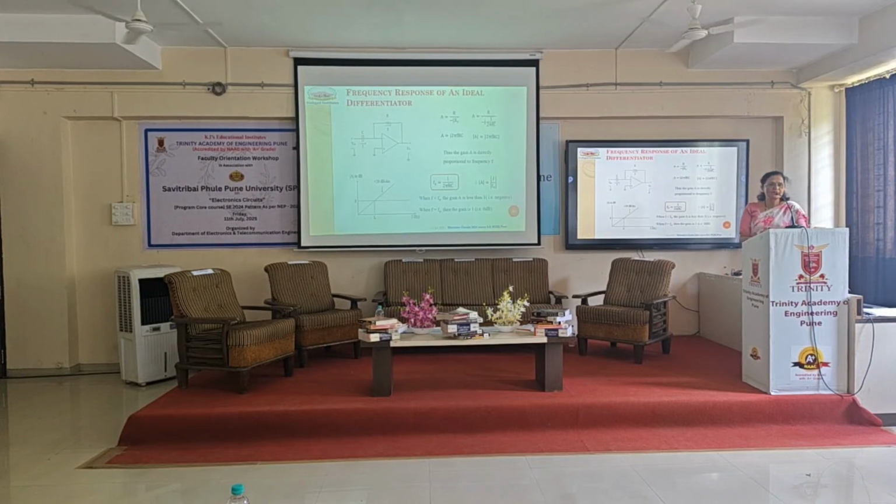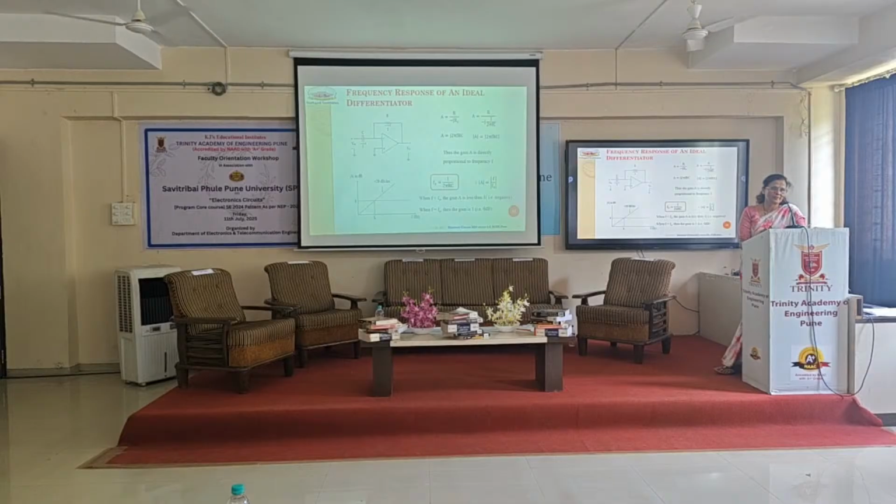Now again, by looking at the response, one can easily understand it is unstable at high frequency range. In order to overcome that, we have to connect an additional component here. Because at high frequency the capacitor becomes open, and due to that the gain is very high, 1/0, infinite gain. That limitation is overcome by using a resistance.